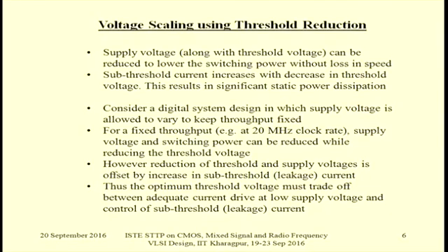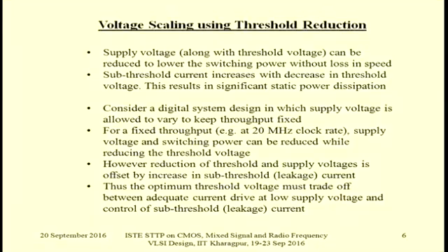Short circuit power, leakage power, one component is subthreshold power, as well as the reverse bias diodes, that is, the parasitic diodes obtained in CMOS devices, as well as the dynamic power. More importantly, dynamic power actually consumes the lion's share of the total power, but this leakage power also we have to consider. So consider a digital system in which the supply voltage is allowed to vary to keep the throughput fixed.